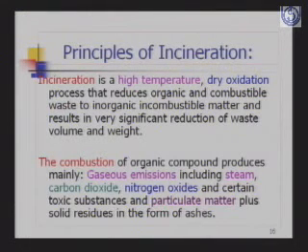What are the principles of incineration? Incineration is a high temperature dry oxidation process that reduces organic and combustible waste into inorganic and incombustible matter and results in a very significant reduction of waste volume and weight. The combustion of organic compounds produces mainly gaseous emissions including steam, carbon dioxide, nitrogen oxide and certain toxic substances, and particulate matter plus solid residue in the form of ash.